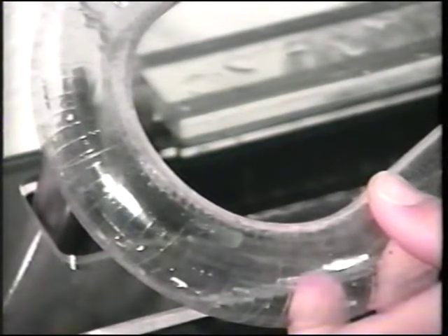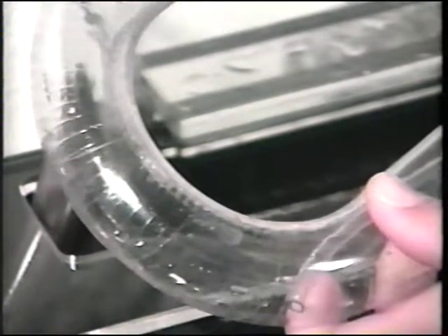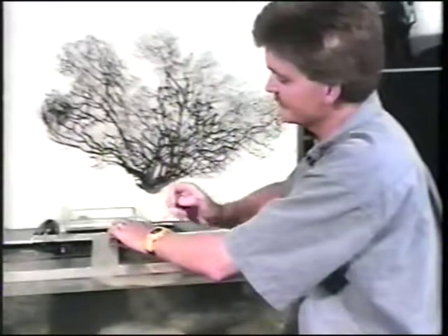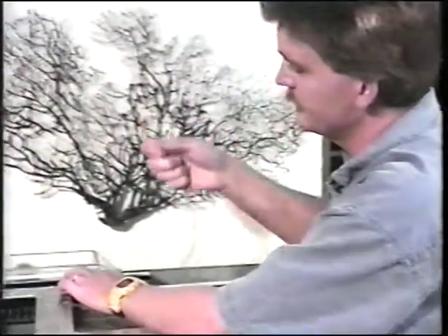After you have filled your tank with water, you must prime your pre-filter by means of a siphon. This is accomplished by inserting airline tubing through the U-shaped pre-filter tube. Then, by sucking air through the airline tubing, a siphon is created. No air bubbles can be present in the pre-filter tube. Once the proper siphon is created, remove the airline tubing.